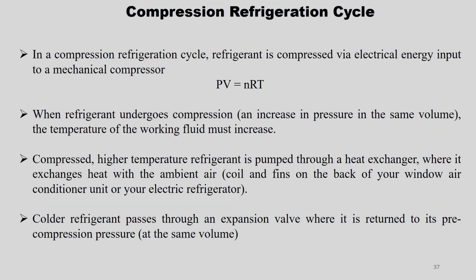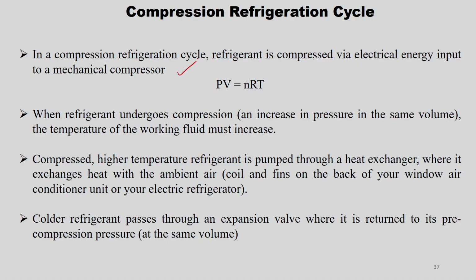The next one is the solar cooling cycle. Before going into the solar cooling cycle, we will see what the compression refrigeration cycle is, how it works, and which component is replaced by solar energy. In the compression refrigeration cycle, the refrigerant is compressed via electrical energy input to a mechanical compressor. It works based on the ideal gas law principle.